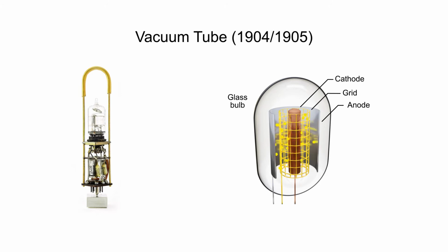The vacuum tube was the first switch with no moving mechanical parts. Its response speed depends on how fast the grid potential can be changed, so it can be changed with electronic speed. The disadvantages of the vacuum tube are its failure susceptibility, its short lifespan, and its high energy loss due to the production of heat.